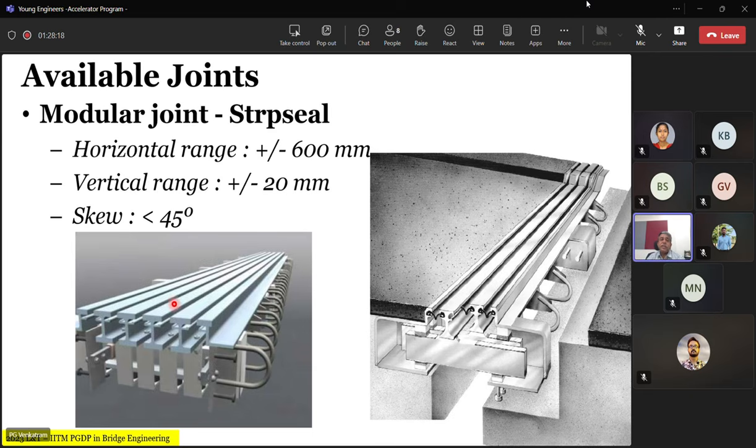It was recently replaced, because that expansion joint, which they had fixed in 1992, had already failed because of non-maintenance, and all the expansion gap was accommodated in one. So there was a very wide gap, and it was identified as early as 2003-4. Unfortunately, with our bureaucracy, the repair works actually commenced only in 2017, 18 or so. I'm not sure. Those who are from Calcutta can confirm that they've actually replaced and fixed that issue now.